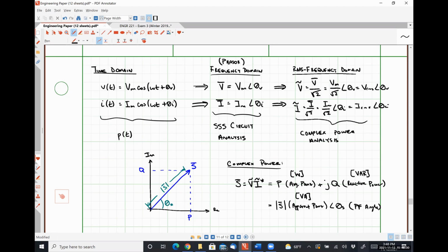Yeah, and the RMS bit there also is telling you it's a magnitude. So it's just the magnitude is the magnitude of the complex number, and the phase angle is the phase angle of the complex number if you're using a polar form representation, right? So I pretty much never do voltages and currents in rectangular form because they don't contain the information that I need to do any analysis easily.